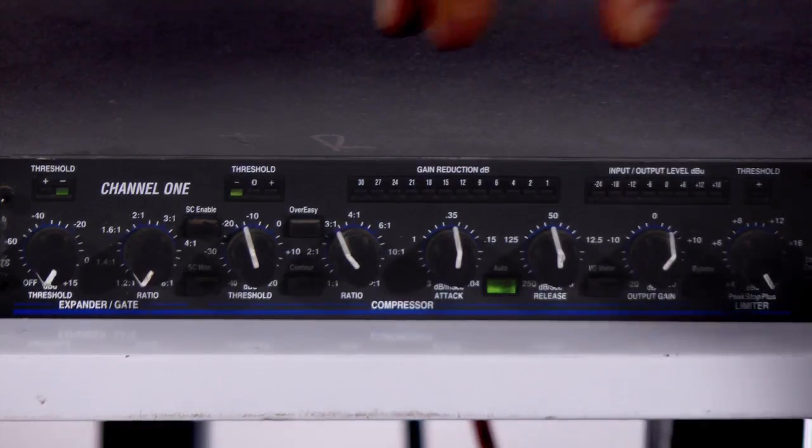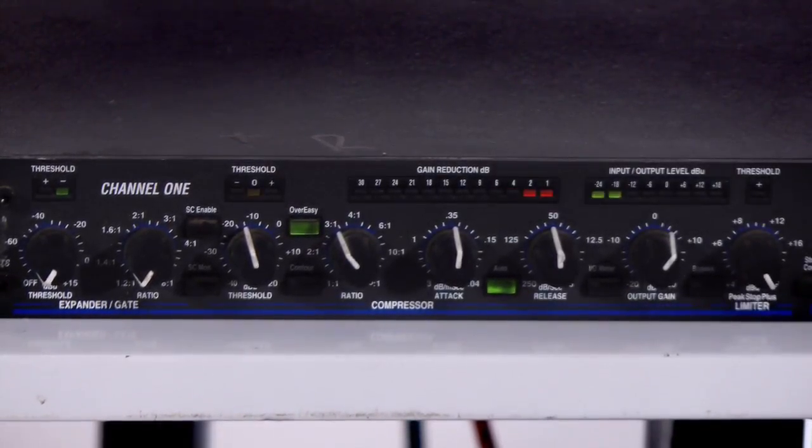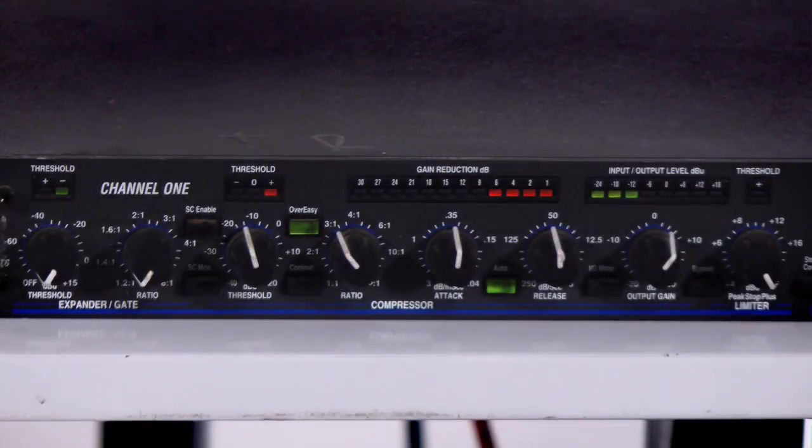A DBX compressor has the ability to turn on a softer knee, and they call this the over easy, quite an American term, but it means that the compressor is very easy around the knee point. Let me just turn that on now. With the over easy set, it means that we should ride the knee without it being so obvious to hear. If you now listen to my voice and the differences between the quiet program and the medium program and the very loud program, we should have a reasonably smooth transition from no gain reduction to full gain reduction.